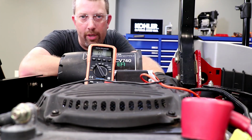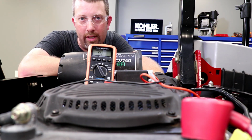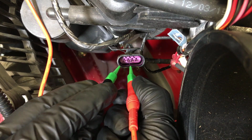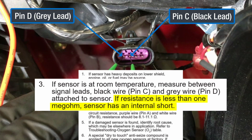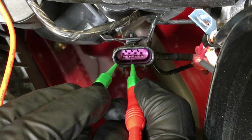Resistance testing can also be done at the oxygen sensor, though test results can be confusing and easily lead to misdiagnosis. For example, the service manual indicates resistance between pin C and D shouldn't be less than 1 megaohm. But every meter I've used to perform this test indicates OL or open circuit, leading one to believe the sensor is defective. Let's take a closer look.